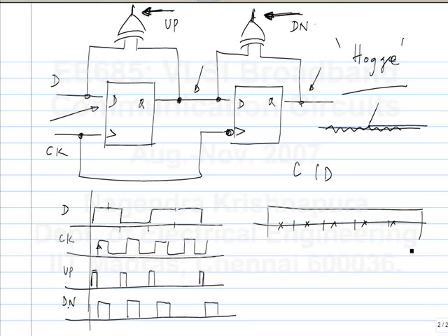Okay. So this is without any other practical problem. This is with everything being ideal. You simply have ripple in the control voltage. So when the transitions stop, it can be at the exact value needed, or it can be higher, or it can be lower. That will accumulate phase error over the consecutive identical digits, and they are not corrected for because you don't have any information when you have identical digits.